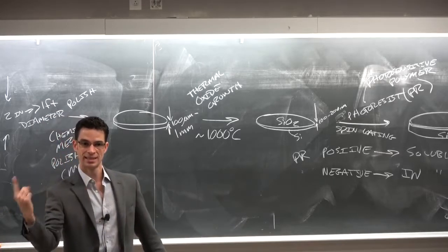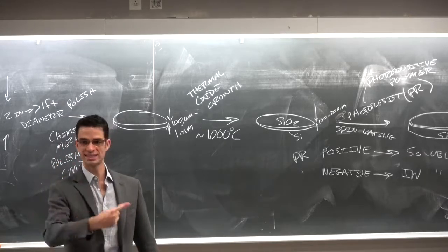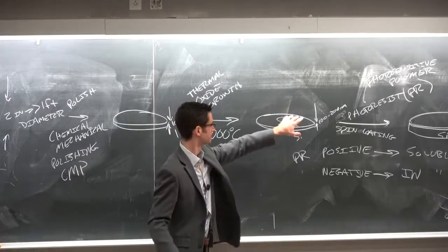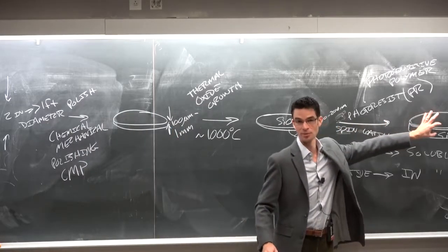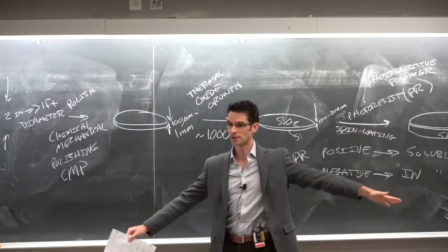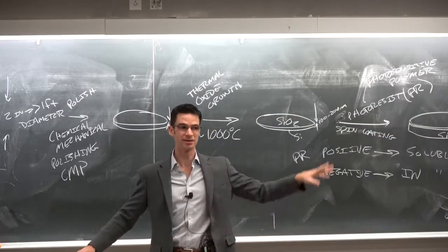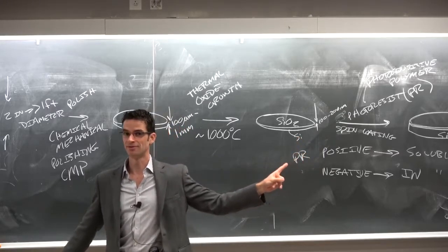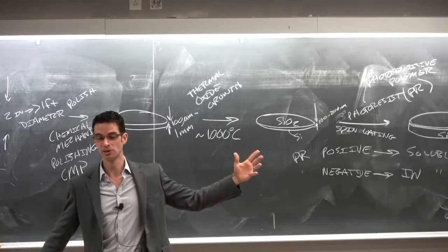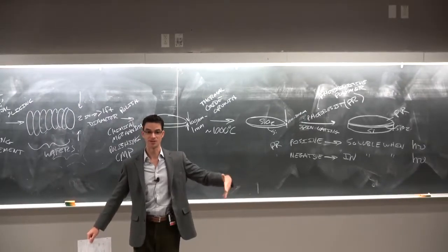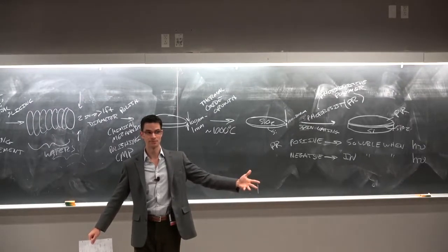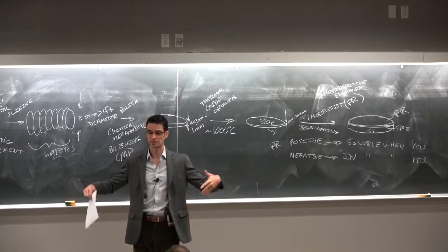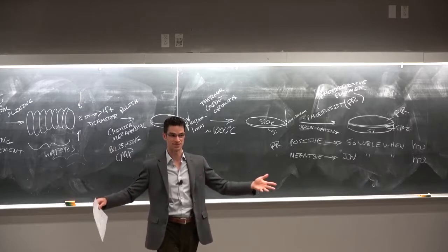And as the excess material is ejected from the spinning wafer, this thins out. The photoresist film or the polymer film or whatever film thins out, and the longer you have it spinning, the thinner this gets. You can also, if you have a solution of polymer that solidifies, if all the solvent is gone, then the faster the solvent evaporates, the thicker the film is, and then stuff stops being ejected as soon as all the solvent is evaporated.